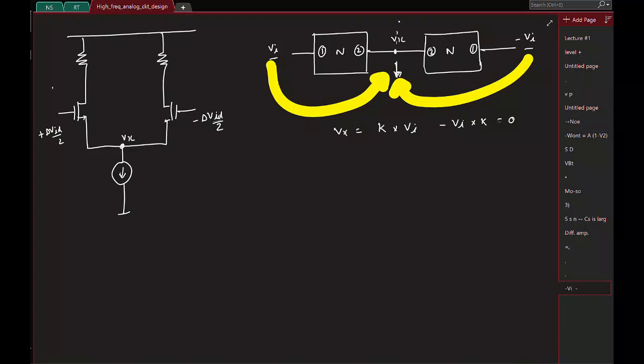And of course for small signals, this is also a linear network. So this is the line of symmetry, and this node here will be at 0, right? This makes the analysis easy. Since this is at 0, and I am interested in finding V out, I can consider only one half of the circuit, say the right half.